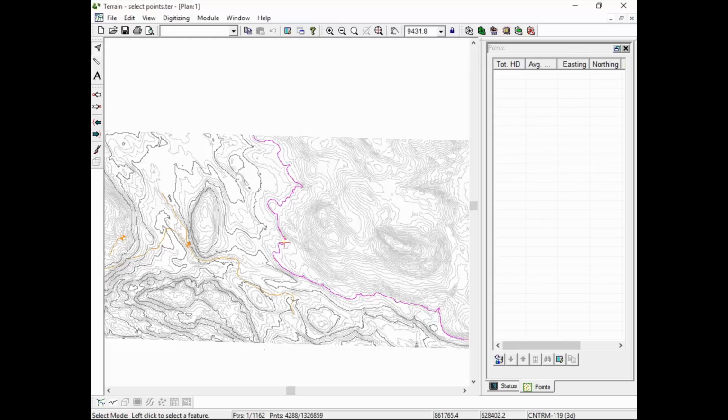Now, I did want to mention that the surface data is used for all kinds of different things. You can use it for making images, for calculating profiles, and in our software, RoadEng, it's often used for roads. One of the things that's kind of interesting about LiDAR is that you can create a surface that goes everywhere, draw your road on it, and you've got cross sections, you've got everything. Let me show you an example of that. Just flip to the location design module.